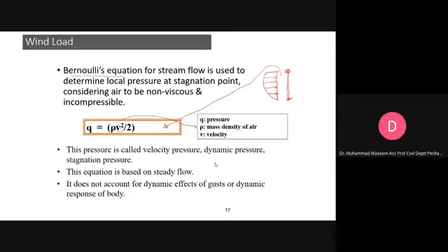The advantage is that these factors or loads have been determined as a result of experimental work. The load factors you see, 1.2 or 1.6, have been derived by a probabilistic theory, which we call reliability theory.